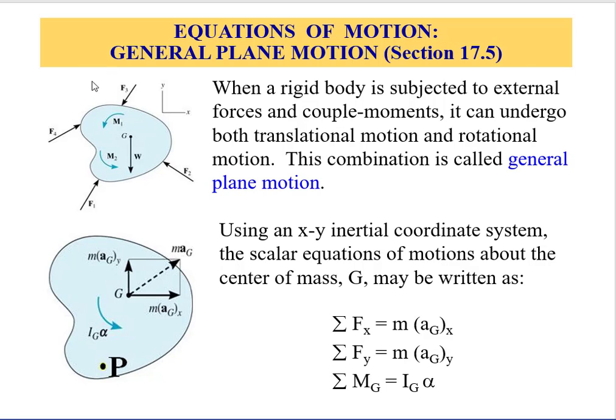All the components of these forces must be equal to the linear inertia along the x, MaGx, as well as the forces in the y direction must be equal to MaGy, and the moments of all these forces and the free moments, taking into account that we choose a proper orientation for the positives, and commonly we use counterclockwise for 2D plane motion.